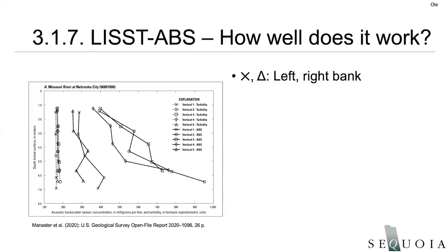If the ABS tracks an OBS or any other turbidity sensor all the time, then there's really no reason for it. But it's because turbidity is sensitive to the same scattering as we see with our eyes. So if water looks turbid, it will seem as turbid water on a turbidity sensor, but an ABS in that same water might rate near 0 because there's no large particles suspended.